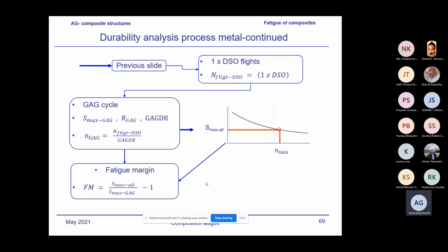So remember this, it's not only the damage tolerance, the durability has to be demonstrated. And damage tolerance is used only for the inspection intervals for the metal. And of course, residual strength. Residual strength is a separate part. So is there any question about this clarification about this durability and damage tolerance philosophy? Everything is very clearly defined in those papers from Boeing, which you can read.